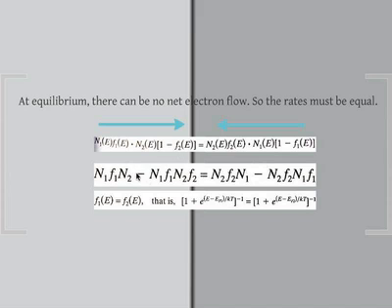If you set them equal and you solve it, essentially what you get is that F1 equals F2. In other words, the Fermi-Dirac distribution on the two sides must be the same. In other words, the Fermi level on both sides must be the same. Okay?